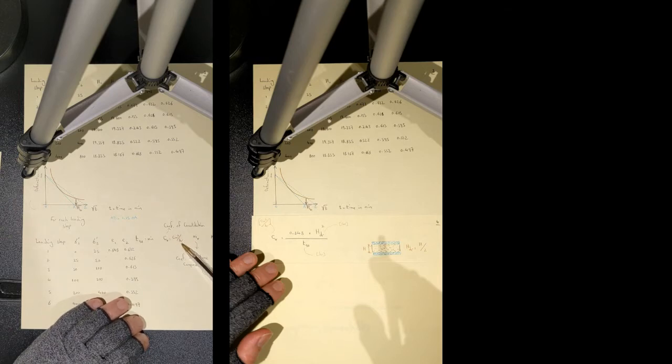You can get a number of different parameters from T sub 90. The first parameter is something known as C sub V, coefficient of consolidation. Now I'd like you to look into the dimensions of coefficient of consolidation. You have centimeters square over hour. So you have time and you have distance.